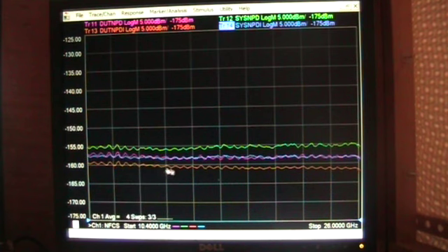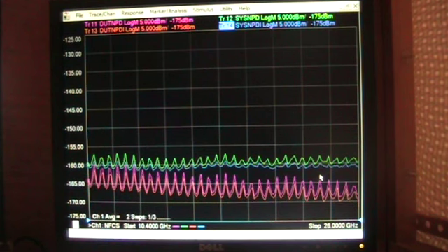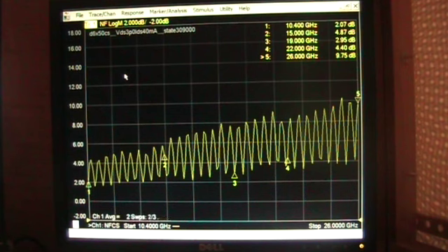Of course, you can see the ripple in this as well, and the assertion we have is that the ripple is very real because of the environment that the device has been placed in. I can see from another screen we've just increased the reflection coefficient to be something very, very high, and you can actually see a significantly higher ripple in the normalized noise, excess noise from the system. And the noise figure is revealing that as well.